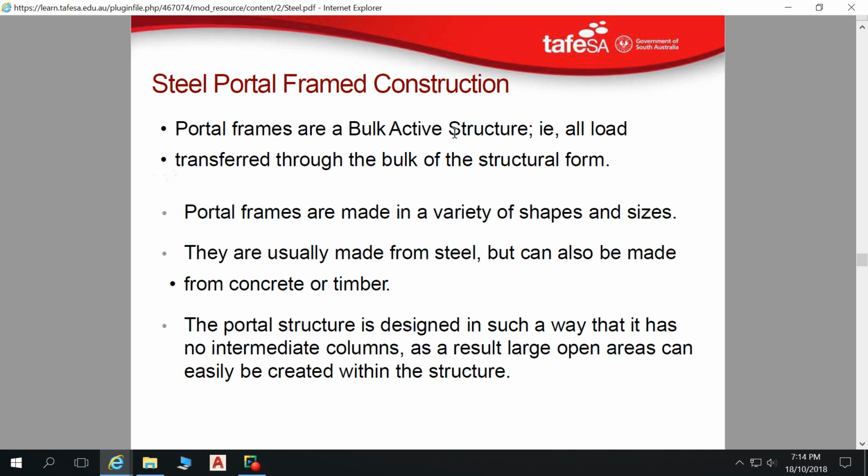That's to create these large open spans, so spans that you can't achieve with timber, even with engineered timber. But it also provides bracing because we've got our columns that are joined to our top rafters, which create a rigid frame, and that provides bracing to the building. So if we look at our timber frame over there, we've got that cross bracing happening on there.